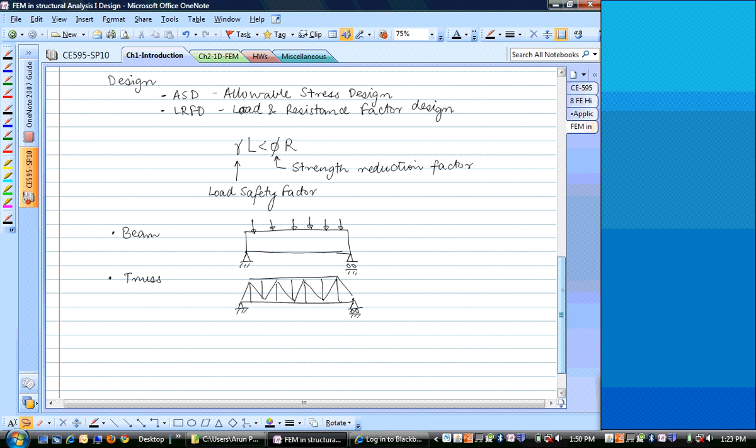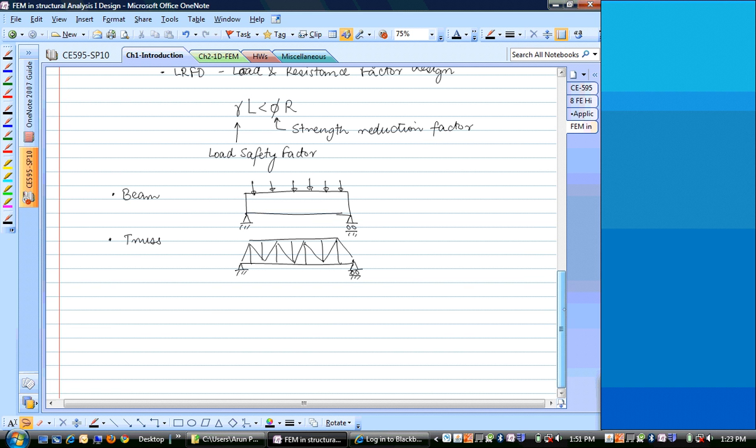If we are given a truss and if it is determinate, we could go method of joints, or we could go method of sections and try to find out all the internal forces, right? And that would qualify as a force method, right? So the point that I'm trying to make here is that you cannot do displacement based method unless you actually assume some material properties. So right now you have just the outline of a bridge. So the first step in any analysis is always a force method. So analyze with force method.